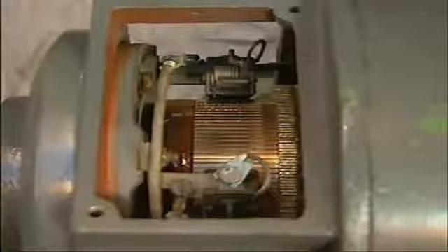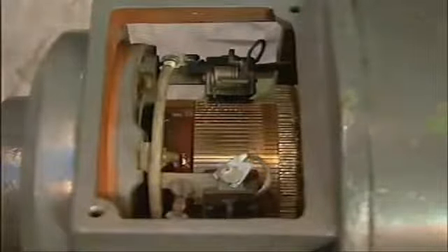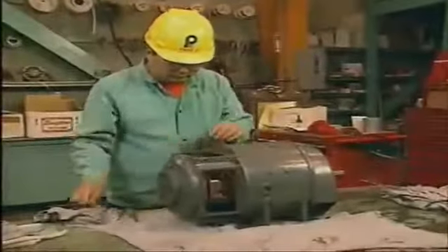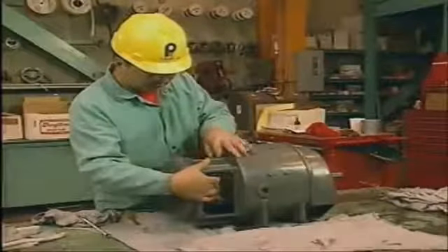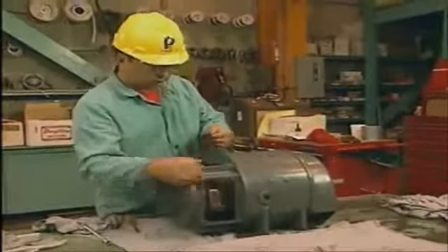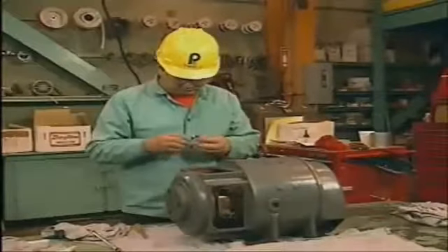Commutators generate a film over their surface that aids the current flow from the brushes to the commutator. The color of this film ranges from a light brown to a chocolate brown when the commutator is in good condition. Care must be taken to avoid removing this film as the commutator is being cleaned. If the film is removed, commutator efficiency will decrease and the brushes may wear more rapidly. Many commutator problems are caused by problems with brushes. Commutator problems can be kept to a minimum by keeping the motor clean and by correcting brush problems as soon as possible.